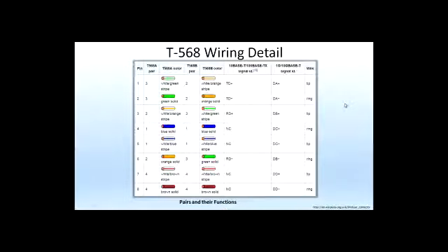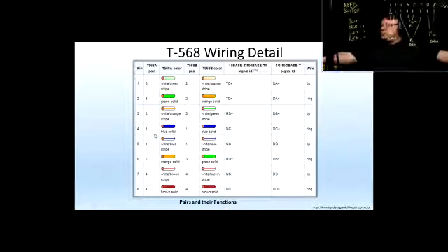All right. The color solids and stripes: when you're holding that, this is the rear of the jack, this is the front of this jack. The blue pair, solid goes on the left and stripe goes on the right. Everything else, you go stripes on the left. So easier to remember is that the stripes are going to the left always, except for the blue pair. It's just how they did that, whoever they are, okay?